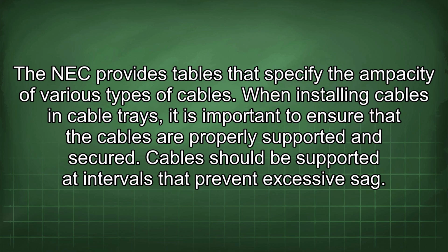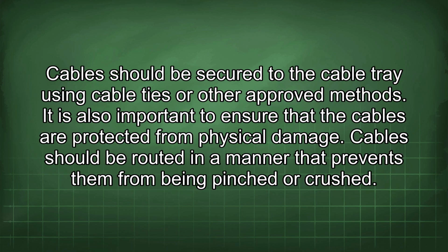When installing cables in cable trays, it is important to ensure that the cables are properly supported and secured. Cables should be supported at intervals that prevent excessive sag. Cables should be secured to the cable tray using cable ties or other approved methods.